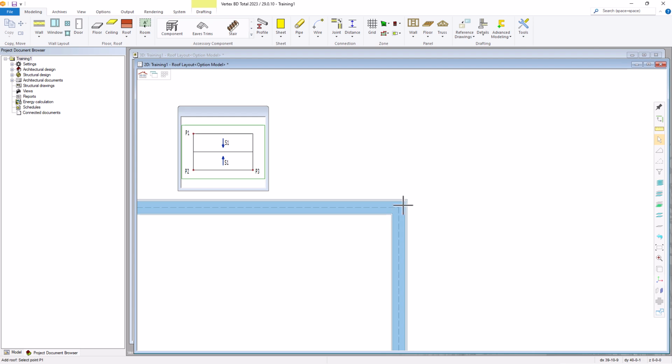So I'm going to cue off this corner, which is our framing corner. Hit Q. And I want that to go over to the right 12 inches. And it needs to go up 12 inches in order for our overhang. So that's located 12 inches over and 12 inches up. And now we can lock it in with the U key.